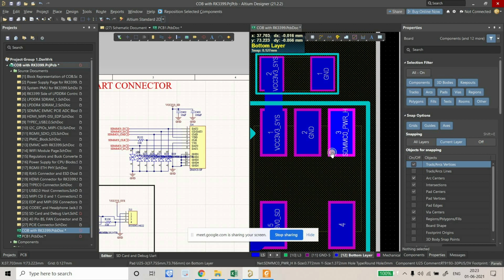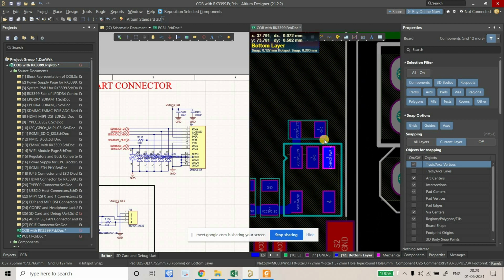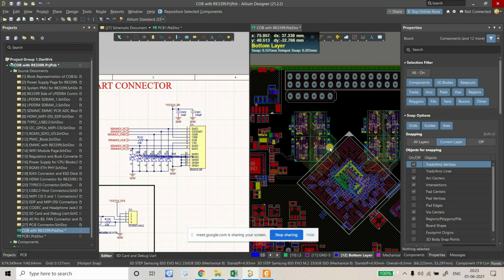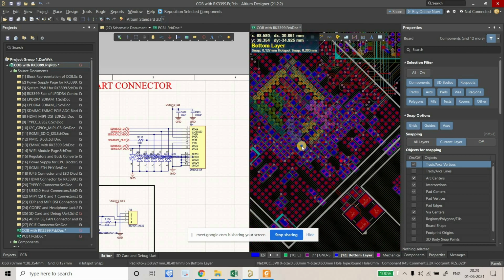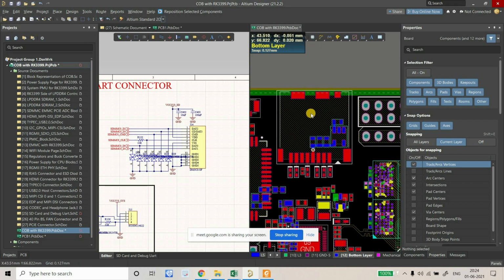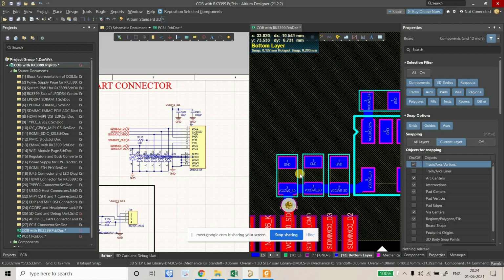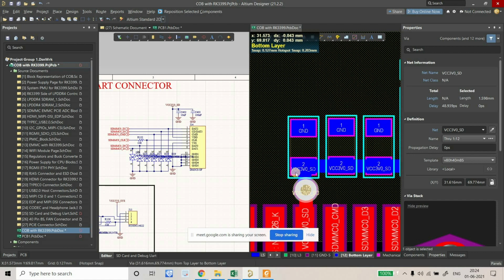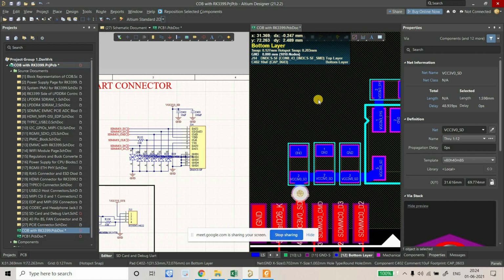And this is the pin which is going somewhere on SOC. Here it is, right? So again, this is not a part of block layout, blockwise layout. This is an example of placing the block, and I'm just going to do that as well. Whenever you are doing the connections or layout, just keep doing the ground as well.